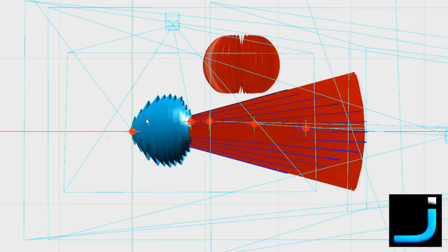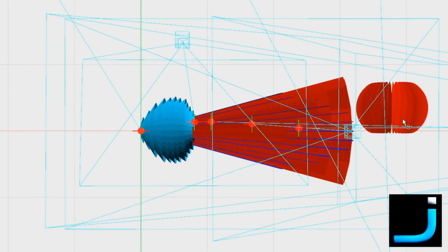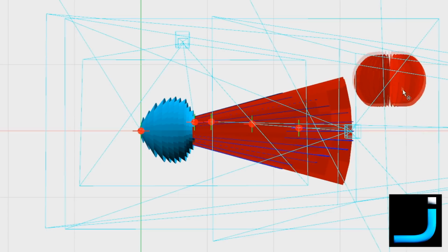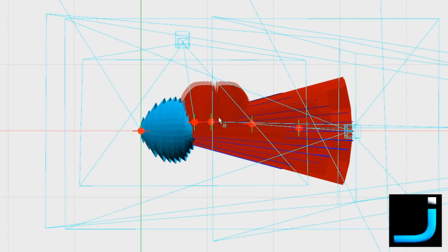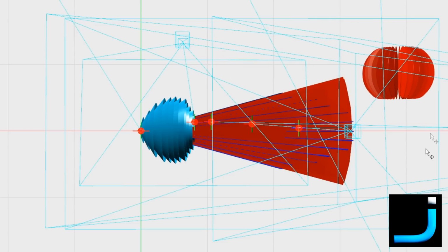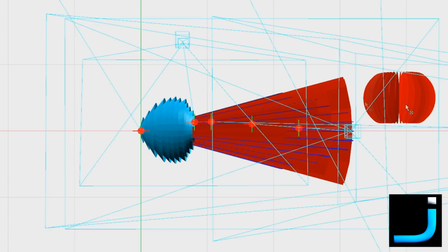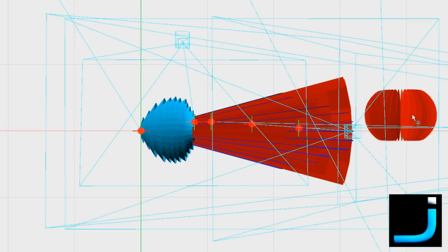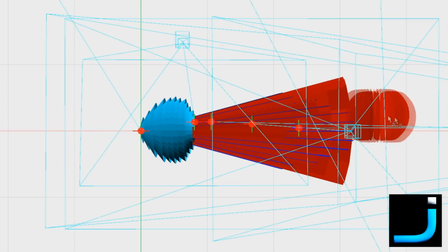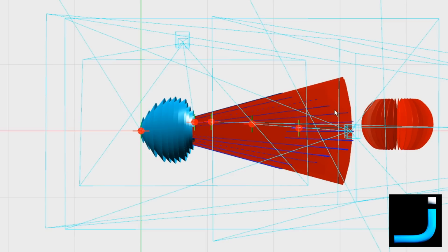I'm just going to flick back to the front view. So, for example, I've got a diversity receiver, and I also have an Oracle connected to a single receiver. The single receiver would have the circularly polarized 8 dB patch antenna, and the diversity receiver would have the two Yagis with linear polarization diversity, and then both of those two systems connected together via an Oracle, which again will look at the best picture and select between the two.